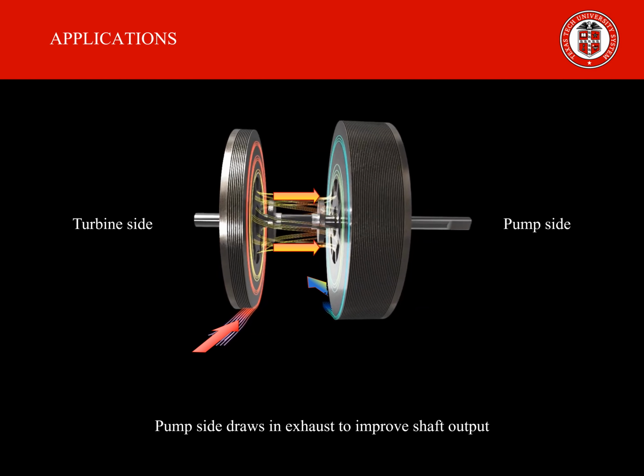The shaft connects to another Tesla turbine, 3 times the volume of the first stage to aid in the removal of exhaust. Note that the central orifices on the outside must be plugged such that the exhaust can only travel between the 2 disk sets, instead of leaving the system. Additionally, the turbine side must be enclosed, while the pump disks may be left completely exposed provided the axial fluid transmission is encased.